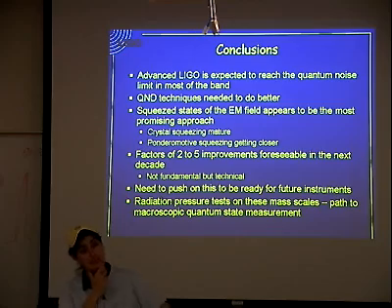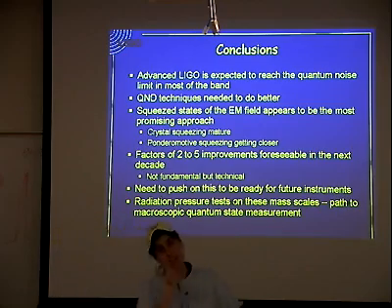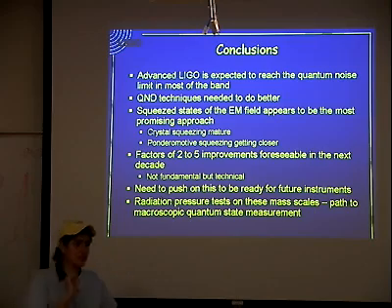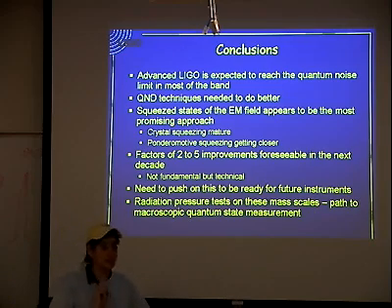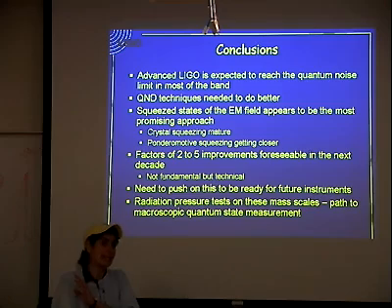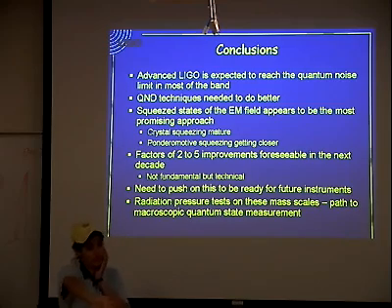The things we've modeled are on that curve, but one other curve which I didn't show because it would take too much work to explain, is that the control noise is actually a big issue for us also. So stabilizing that 5 kilohertz resonance without getting any other control feedback in band has been hard. But I haven't looked at those noise sources. If you want to tell me they're bad news, I'm not listening.